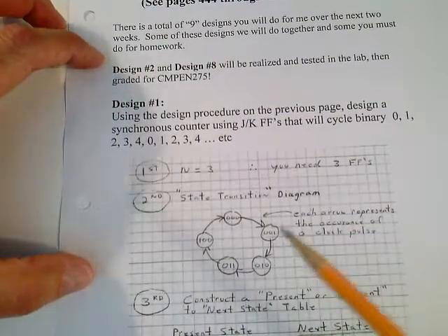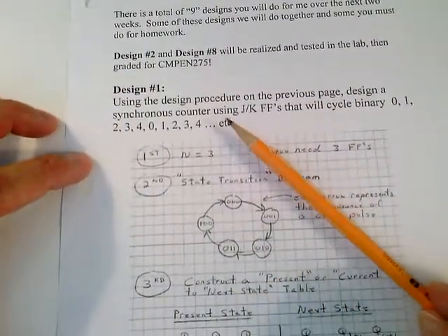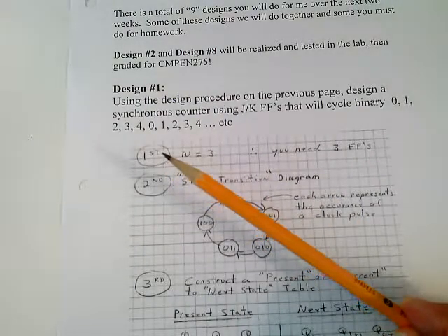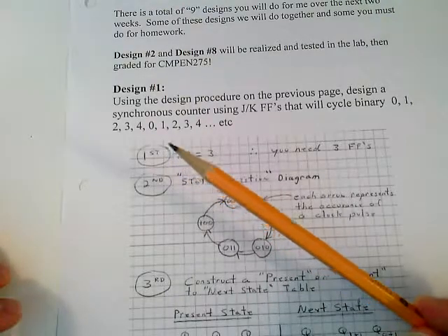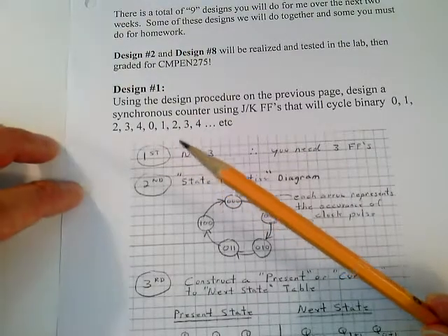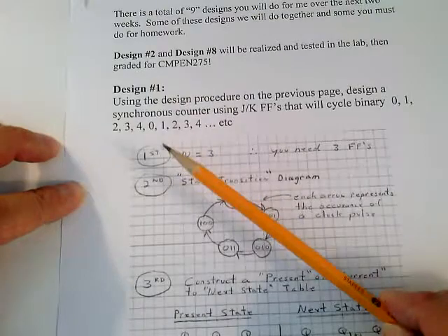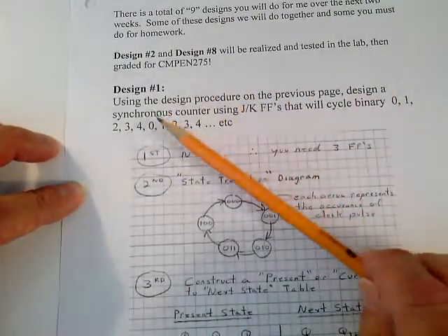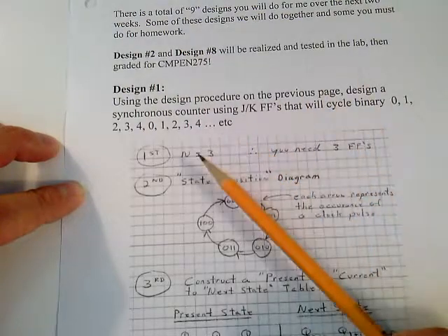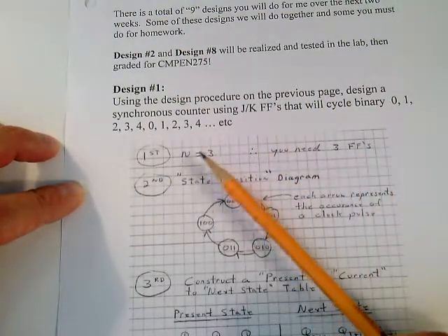So let's take a look at the first step. Here's our specification. The first step, if you look at page number 210, says determine the desired number of flip-flops needed in your design. This is based on either your maximum count or the number of states required in your state machine. Well, after giving it some thought here, we have to count up to 4. If you're going to count up here to 4 and you're going to do that with a binary counter, you need to have 3 bits. Think about that. You need to have 3 bits, a 1, 0, 0, to count up to 4. So you need 3 flip-flops. So n is equal to 3. That's your starting point on all these designs.